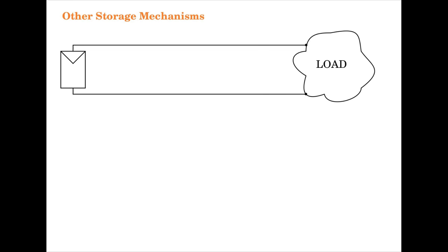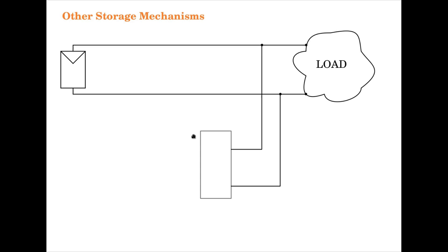Therefore, we connect an energy buffer at this point, the point at which it can supplement along with the PV panel. So the energy buffers in general will have an interface block here, and this interface block will connect with the actual energy storing device, which we will call the energy buffer, and this would be called the power interface.